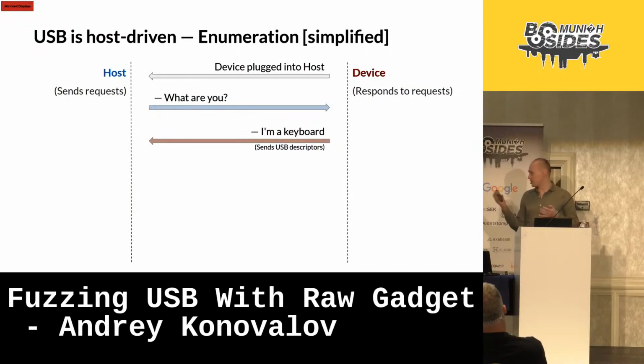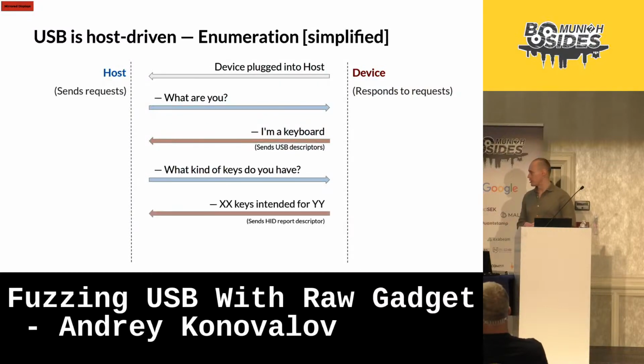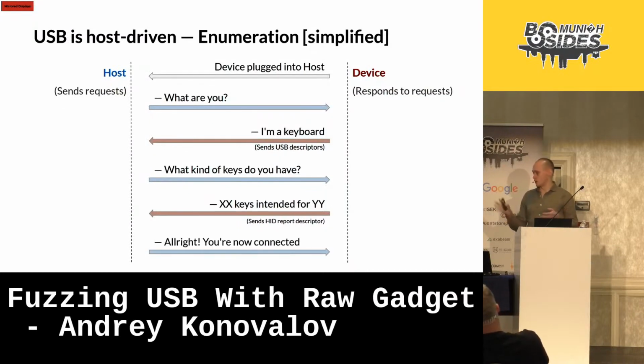Now again, the device cannot just start communicating. The host knows how to handle keyboards, and now the host asks the device, what kind of keys do you have and what purpose do they serve? And now the device responds, I have this many keys intended for this purpose. And now the host says, all right, you're now connected. To which the device will respond, okay. This didn't fit into the slide.